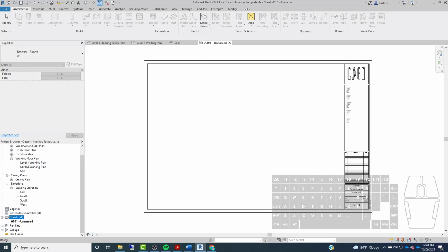All right, and if you remember back from the prior lecture, your plan drawings are going to be the 1 series. So first we have our discipline designator, so that's the A. Then our second one is going to actually designate the type of drawing, the sheet type. And then these two numbers at the end are just telling you which number in the series of that type the sheet is.